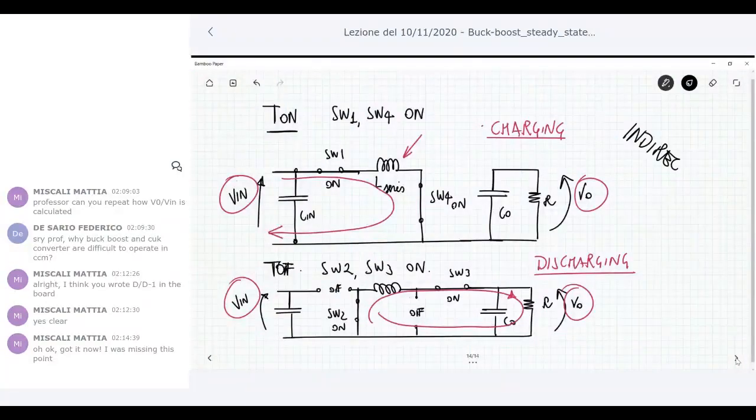And as the buck boost, it is an indirect converter. Remember that we define a direct converter, like the buck or the boost converter, as one in which there is a phase in their operation in which there is a direct connection between the input side and the output side, or an indirect converter like the buck boost, in which this does not happen for any time interval. Okay, so these are the same properties of the classical standard buck boost.